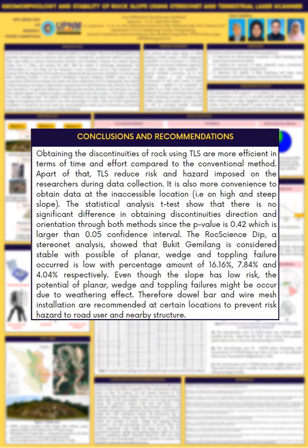In conclusion, obtaining the discontinuities of rock using TLS is more efficient in terms of time and effort compared to the conventional method. Apart from that, TLS reduces risk and hazard imposed on the researchers during data collection. It is also more convenient to obtain data at inaccessible locations, such as on high and steep slopes.